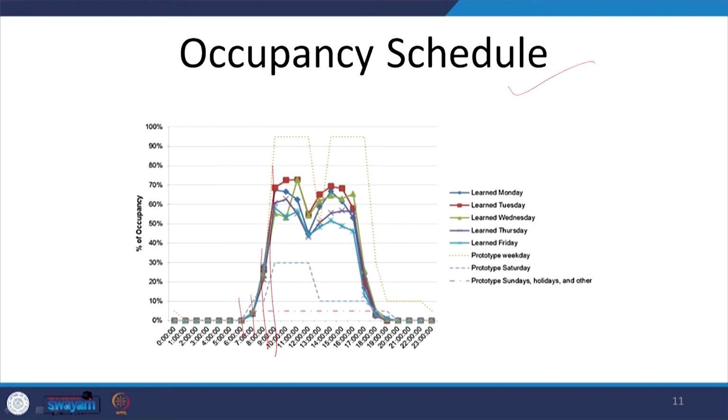When we are proposing, when we are calculating and estimating the performance of the building, we will assume the occupancy to be higher, somewhere close to 90%. Sometimes, for example in buildings like hospitals, the occupancy may be taken as much lower, at 75%. When we are talking about hotels, the occupancy may be taken even lesser, at 60%. So, depending upon the use and the type of the building, the occupancy schedule will vary.